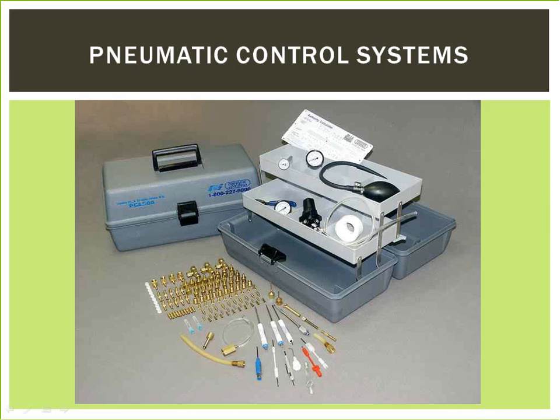Some of the most common problems related to pneumatic controls include thermostats. It is the device that is most interacted with. As such, it is the most subject to failure. If you are called out on a temperature call, first check the source pressure at the thermostat. Make adjustments as necessary. Verify that output pressure is correct based on the setting of the thermostat. If the thermostat does not operate within parameters, you can attempt to calibrate. If calibration is not possible, replace the thermostat.